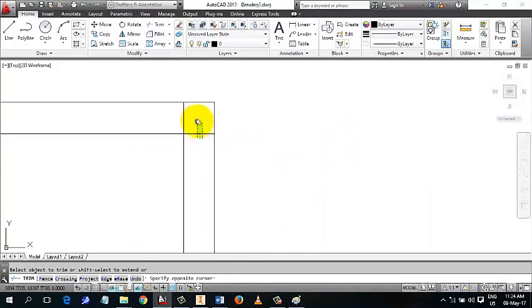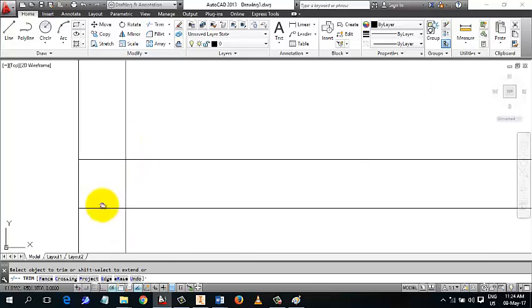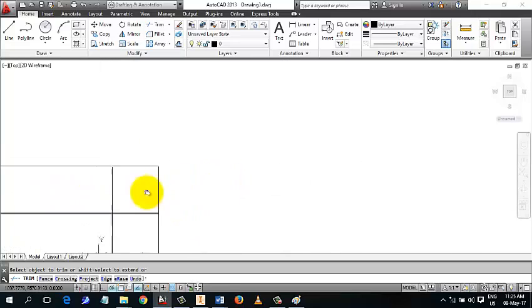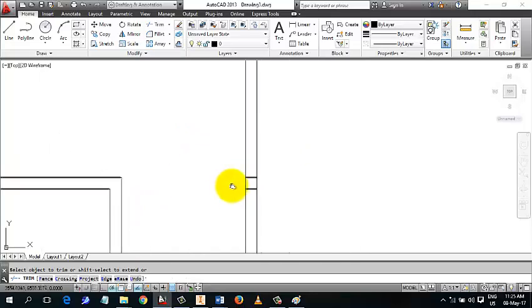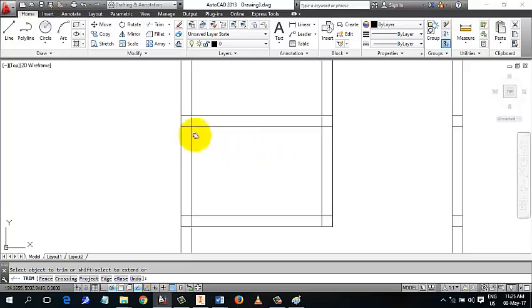The block must intersect, have you? You trim that. That kind of a selection, what do I call it? Cross selection, okay? Anything it touches will be selected. So, guess what will happen here? It's not going to work. There's no cutting edge. It's not cutting anything. It's inside it. So, we are going to delete that later.